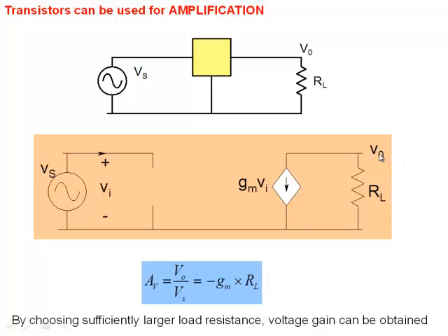Which means that the output power that you get here divided by input power must be greater than 1, which is obvious in this particular case. Okay? And so here I'm talking about a voltage amplifier, and I've said the condition for voltage amplifier, I mean, if you have a situation like this, a transistor like this, it's very easy to get a voltage amplifier here. Okay? But keep in mind, for a 3-terminal device to be called an amplifier, in general, you have to have power gain. Without power gain, you don't have an amplifier. Okay?